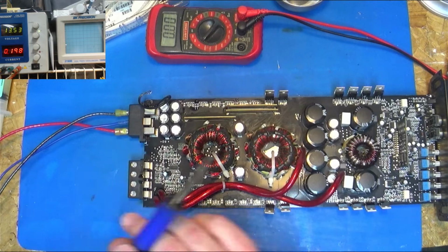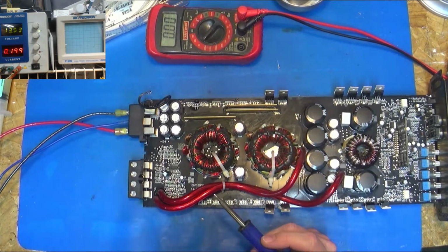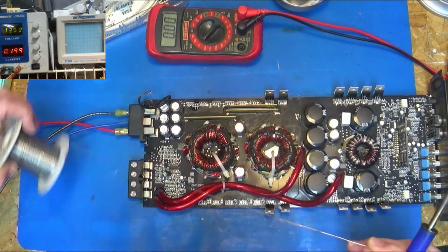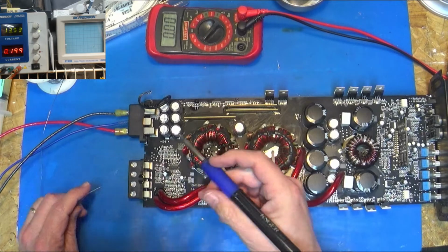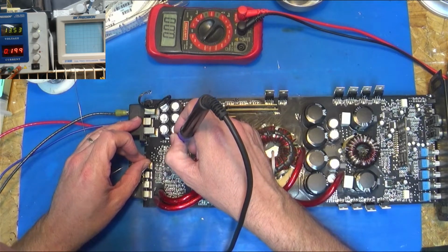And I'm going to add leaded solder to all of them. Just rub it on each of the 3 legs and kind of blend it in with the lead-free solder. And then I'm going to get my hot air rework station and just remove them instead of trying to get them all out.